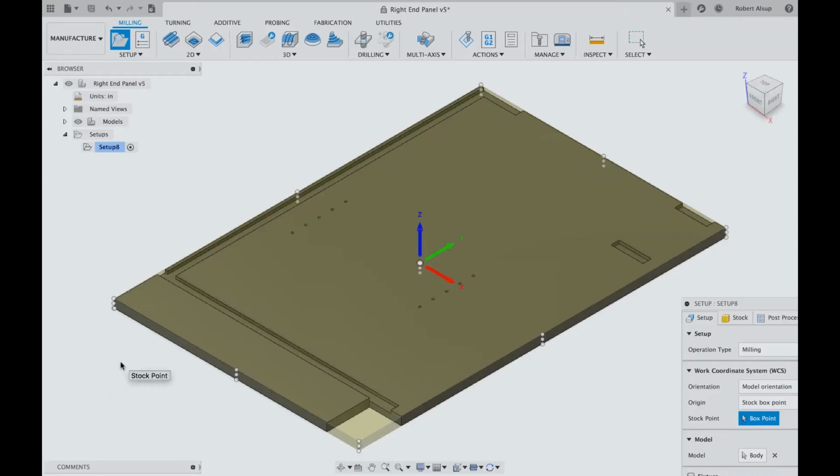Now, why did this work out automatically? Well, because when I created that very first sketch and I determined the work plane, I picked that horizontal plane because I knew that corresponded to the machine itself. That's not always the case. Sometimes you get this part and it's sitting up on end. What if it's part of an assembly of a cabinet or something? And you may not be able to rotate it because it interferes with the cabinet assembly.